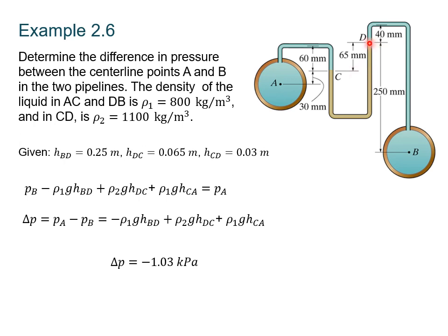So what's the pressure difference between here and here? It's the density of the lime green, rho 2, times g, times this height differential, which is 65 millimeters, right? So we add on, because we move downward, rho 2, the density of the lime green, times g times the height from D to C, here to there. So now we're over here because we can move horizontally.